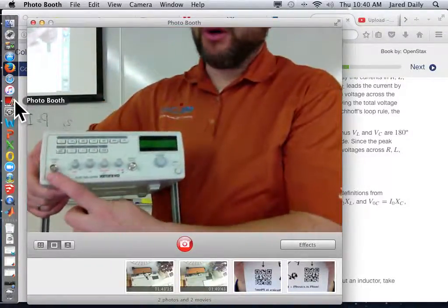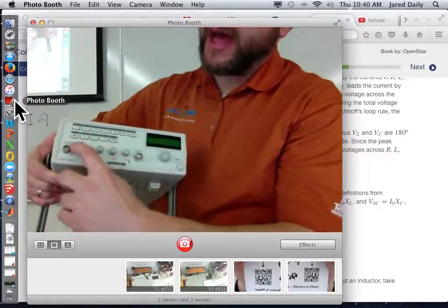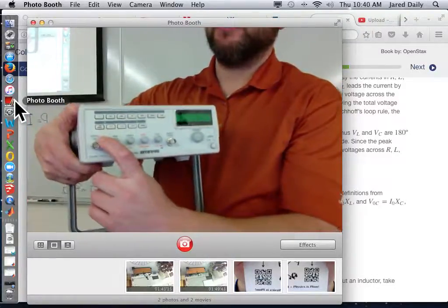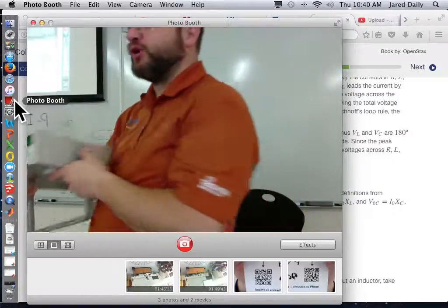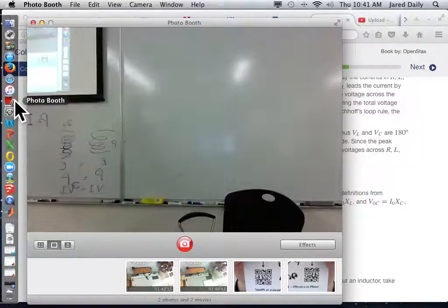And on the output that we plugged into it says right here the output is 50 ohms. Well, the output is not pure resistance because this is an AC circuit. And AC circuits always have reactance. They always have at least inductive reactance, but they also probably have capacitive reactance. There are all kinds of capacitors and inductors inside this thing in addition to resistors, and all kinds of loops of wire that aren't intended to be inductors but are anyway.